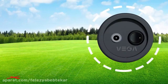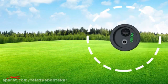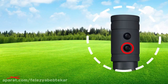Select the starting point of the scan from one of the 4 corners of the place, and turn on your device using the button on the top of the sensor. There are 2 other buttons on the sensor. The first one is called New Line, and the bottom one is for scanning as well as Ground Balance.